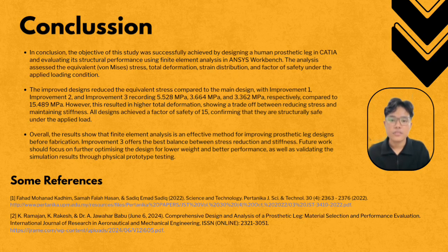All designs achieve a factor of safety of 15, confirming that they are structurally safe under the applied load. Overall, the results show that finite element analysis is an effective method for improving the human prosthetic leg design before fabrication. So Improvement 3 offers the best balance between stress reduction and stiffness.